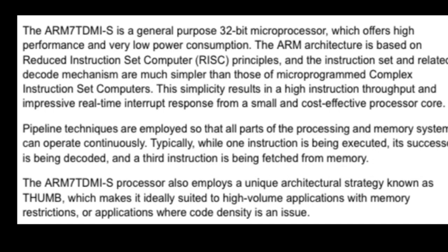Here the architecture is based on the RISC principles. So what is RISC? It is nothing but reduced instruction set computing. When you compare with complex instruction set computing, this particular instruction set and the decoding mechanism are much simpler. Because of this, it offers a high instruction throughput and an impressive real-time interrupt response time from a small and cost-effective processor core. As everyone knows, we use the pipeline technique: when one instruction is being executed, the second instruction is being decoded, and finally the third instruction is fetched from the memory.